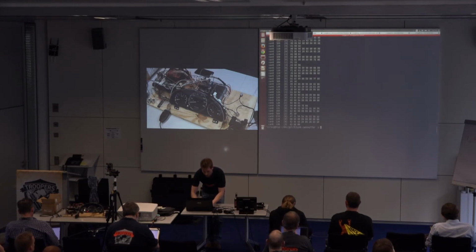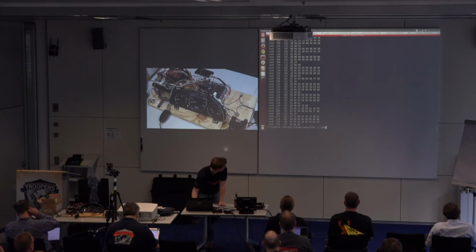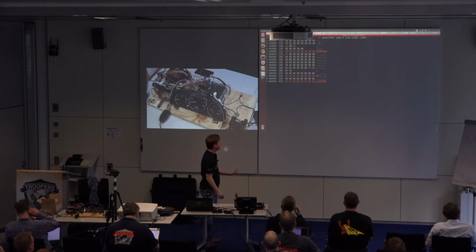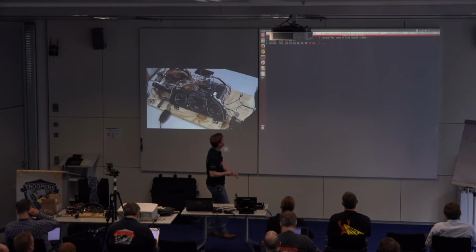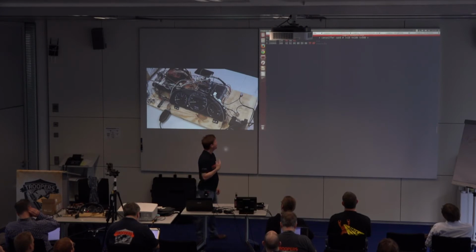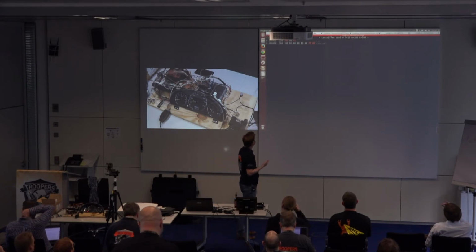The way you really want to do it is group it by the arbitration ID. In this case, CAN Utils comes with cansniffer. Most utilities, if you're ever working on actually reverse engineering one, they're used to reverse engineering, this is how they'll do it. And what just happened there is it groups them by ID. The bytes that are red are the bytes that are changing.